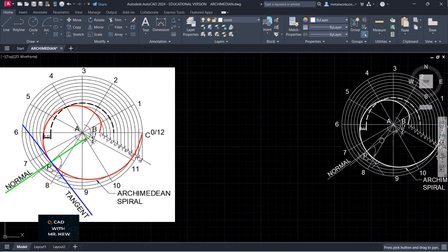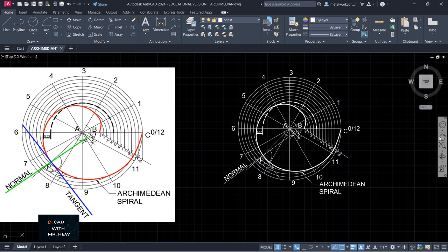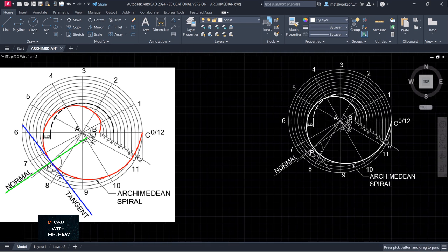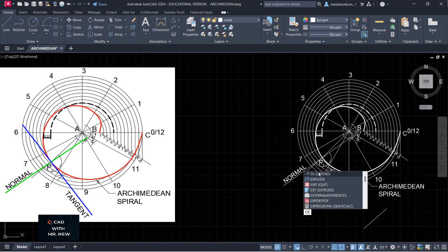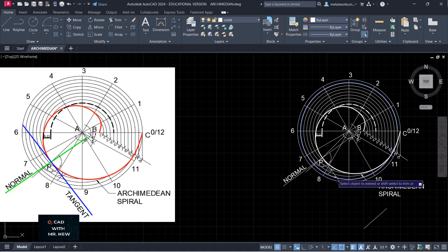I'm actually gonna shift it. All right, so we're gonna shift it back here to center. We're gonna draw a random construction line down here as a boundary to extend it to, and then we delete it. All right, so we go again. Extend, shortcut for extend, EX. See?